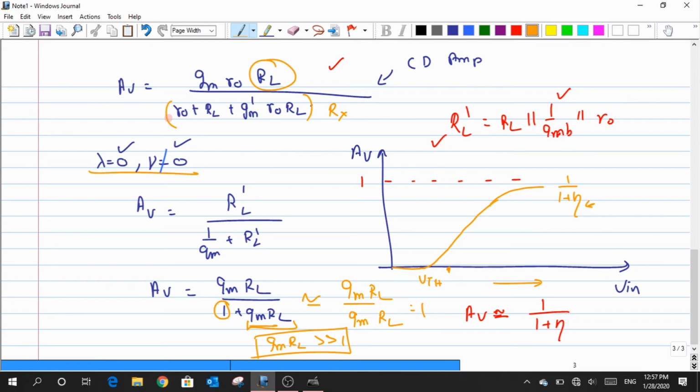Say for example, I have designed a very high gain circuit, let us take our simple common source amplifier. I have done something here to get a very high gain. I will not worry about whether I worked with RD or the W factor, but the point is that I have got too much gain out of the circuit. Now I have a load to the device, and that load is a very small resistance. What happens the moment I connect this load directly to this CS amplifier? Let me replace this with the current source load.